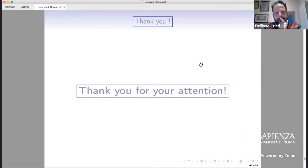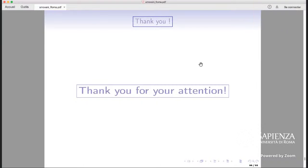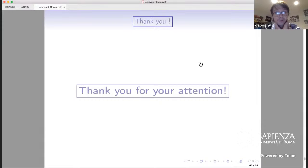I know that there are some works trying to optimize the orientation of the build direction, which rely on more geometric criteria. For instance, I think there is an article by Benny Bogosel and Grégoire Haller addressing this issue, among other articles probably. But if I'm not mistaken, they rely on more geometric criteria. I don't quite see any easy means by which we could couple this with the model here. You would have to take derivatives of the slices in some sense with respect to the orientation of the slices. So it seems a bit, I don't quite see how we do it.